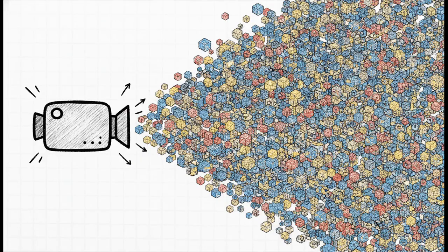And to put that data volume into perspective, we aren't talking about your standard compressed internet video here. A single second of just one of these camera feeds generates over 530,000 network packets. That is pure, raw, uncompressed pixels. We're talking over 5,000 megabits per second of data for a single feed just to ensure the picture is absolutely flawless before it ever even reaches a broadcaster.